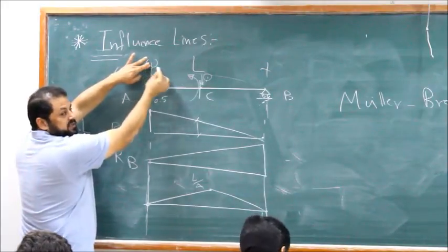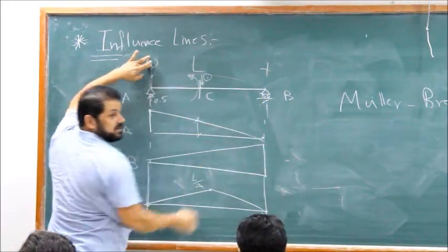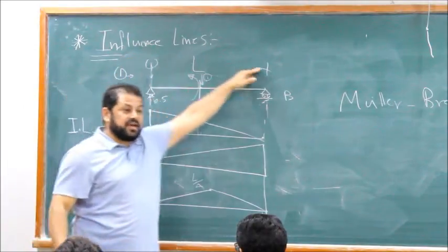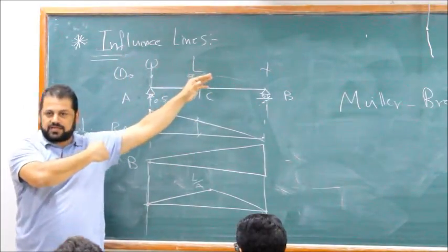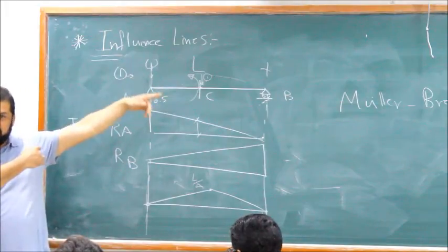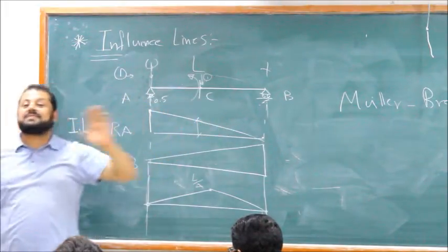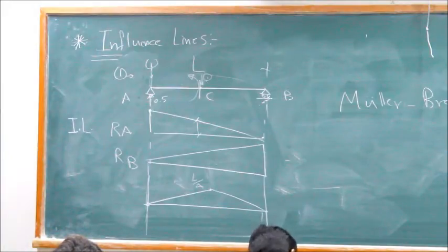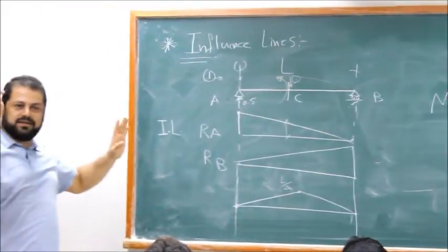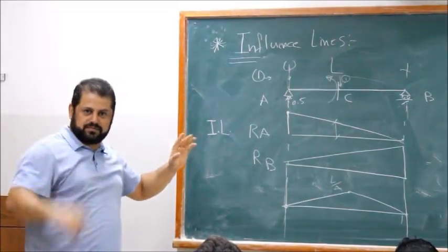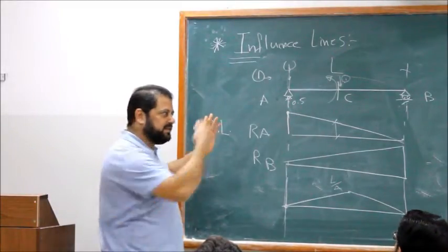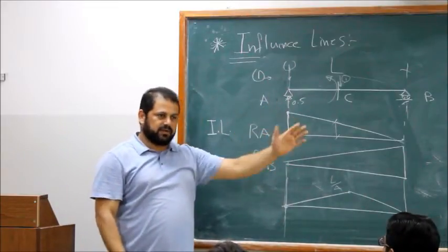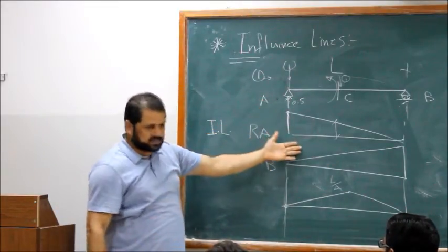A straight line. So the deformed shape after moving this location, that's the Müller-Breslau principle, is to some scale the influence line. You have to apply a scale factor. In a statically determinate structure it is 1. In an indeterminate structure there will be a scale, we will calculate it. Don't worry about this. Just review this one with me now.